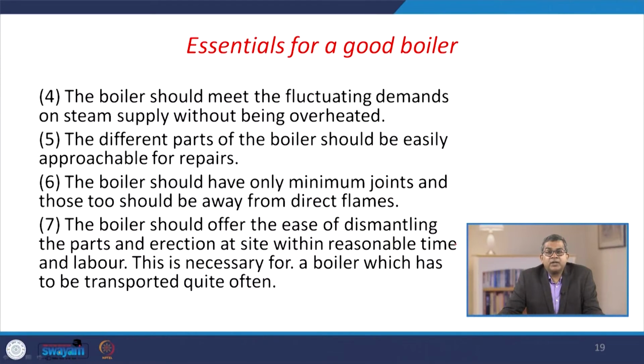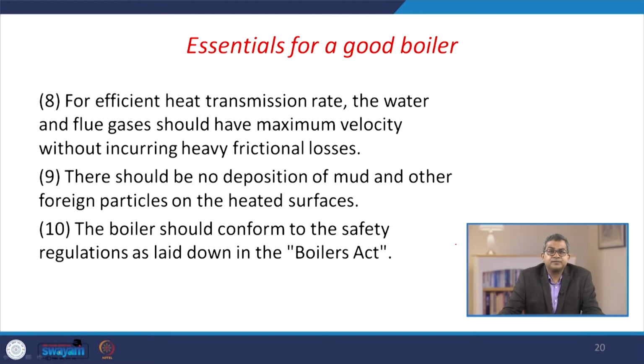Boiler is the heart of any industry. The boiler should have only minimum joints, and those too should be away from direct flames, otherwise expansion may create a severe problem with respect to safety. The boiler should offer ease of dismantling the parts and erection at site within reasonable time and labor. This is necessary for a boiler which has to be transported quite often.